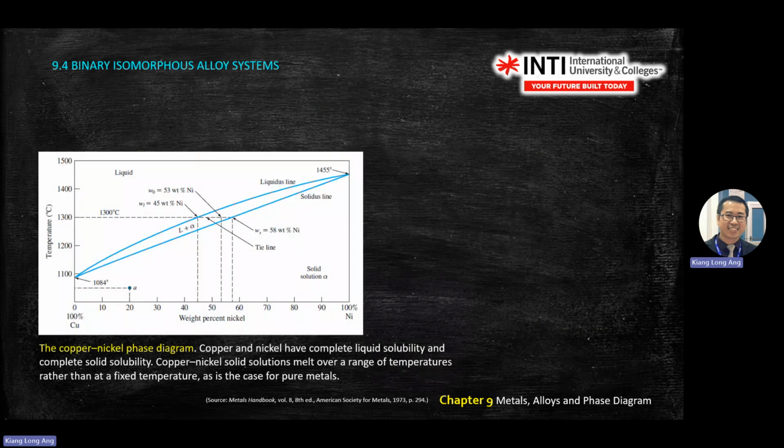Okay, the first real metal, very popular, is the copper-nickel diagram. No need to memorize, but you should be able to understand or find the correct graph. You will see more than 3 kinds of graph, the same shape but with different axes, different temperatures, different materials. The first thing you look at in a phase diagram is the y-axis, temperature. Your x-axis will be the weight percent axis.